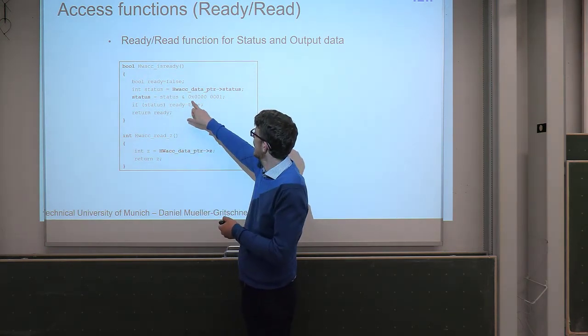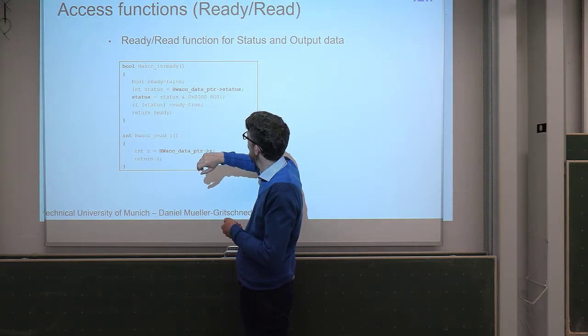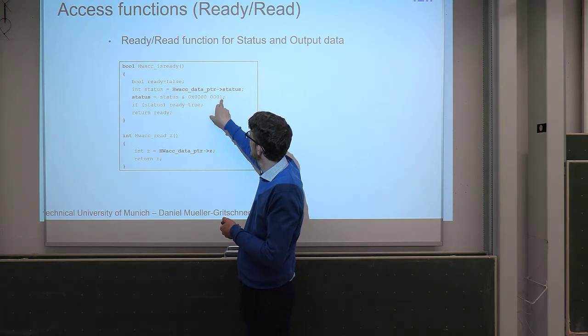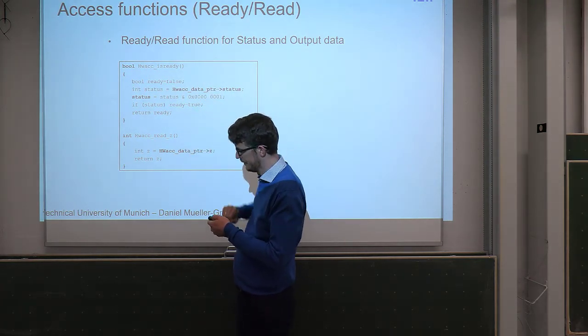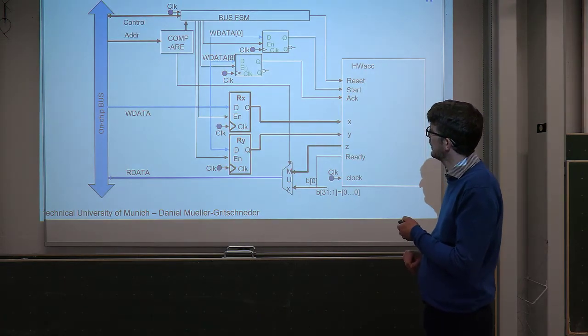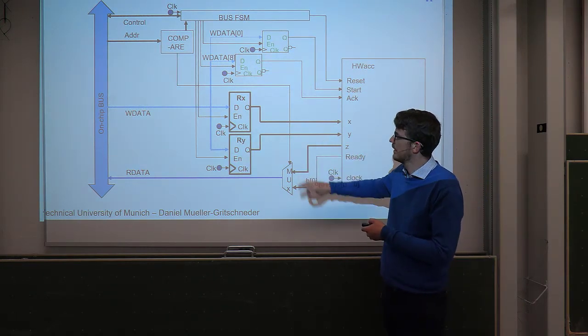and then we are saying, okay, is the lowest bit of the status 1? So we're basically masking everything else out, we are just looking at the lowest bit, and we're seeing whether this is run, and if this is run, we know we are ready. Then we know that actually in set is the valid signal.